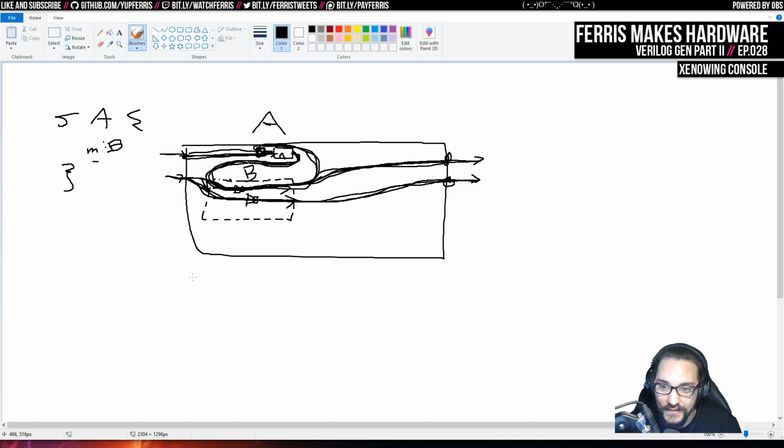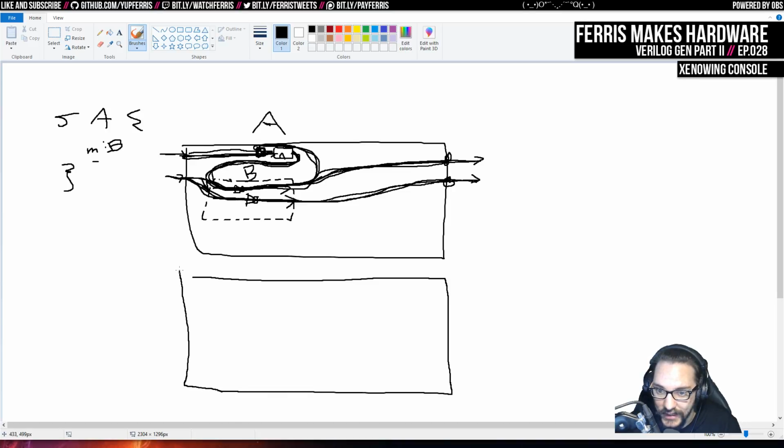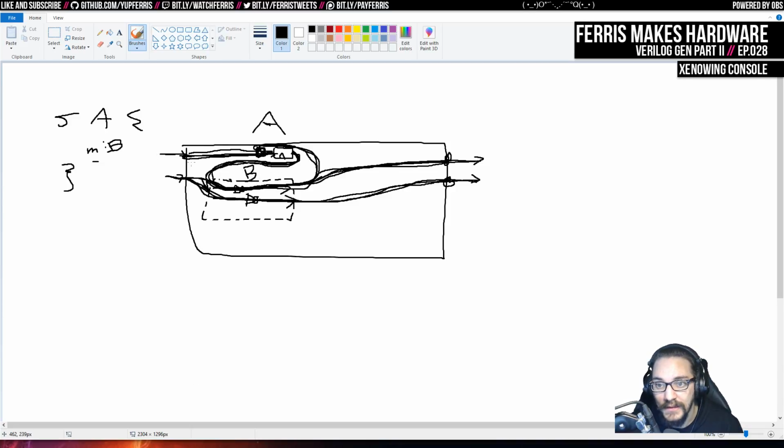And if we're going to generate sim traces, which is something eventually that I kind of want to do, we can still have information in this module that knows about what this hierarchy was. So we can still generate a hierarchical value change dump where we have that hierarchy preserved there, but then still in the evaluation of this model, we never have to track any of that hierarchy again. So that's why I did that in sim. We can sort of invisibly flatten everything, and that makes our life a lot easier.